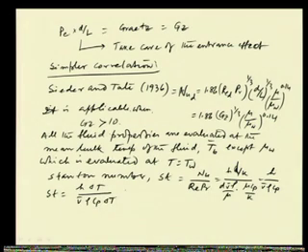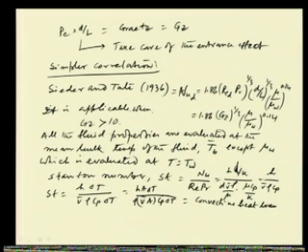We can understand that if we again multiply by the area A, it is hA delta T by rho V bar A, which is the volumetric flow rate, into rho, the mass flow rate, into Cp into delta T. So, this is heat transfer due to bulk flow. So, we can say it is convective heat transfer divided by heat transfer by bulk flow.